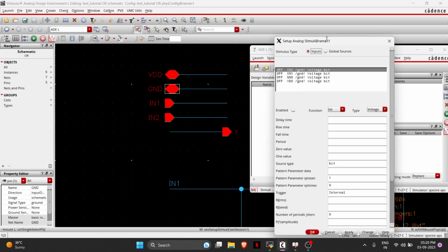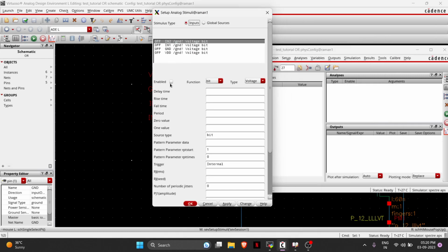Stimulus. First, we need to enable this thing from here. Define kind of activate your phones and then define the voltage. You can give 1.2 volts of pulse delayed by 10 nanosecond. Pulse of 10, this is 20. Okay, you can define all of it.